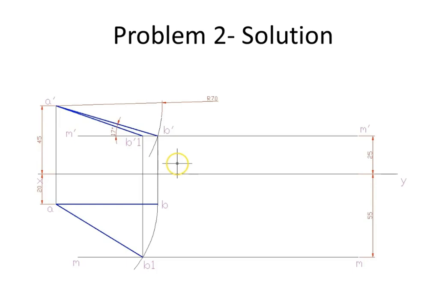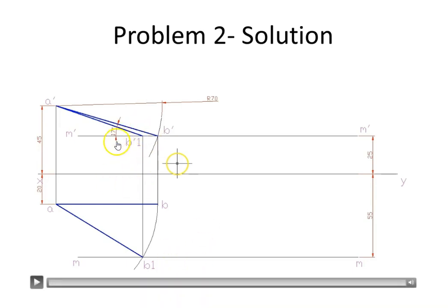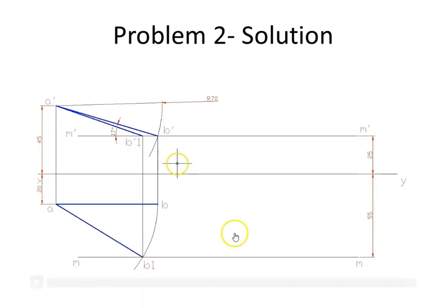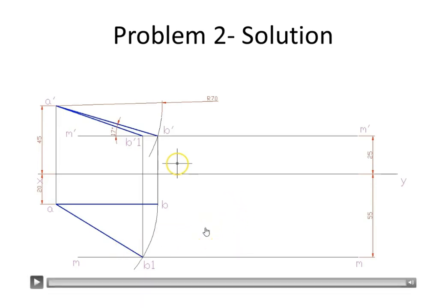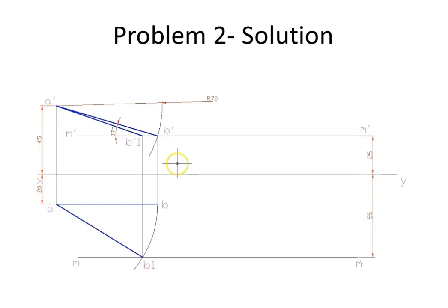What we would have done is, as in the previous case, we would have drawn a true length in this side as well, that is in the top view side as well, and we could actually start by keeping A as center and draw another line with the 70 mm radius and cut on this projection, cut on this locus, and that line, if you take the inclination of that line with the horizontal, that inclination will give you the inclination with VP.